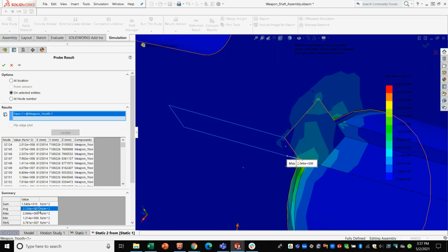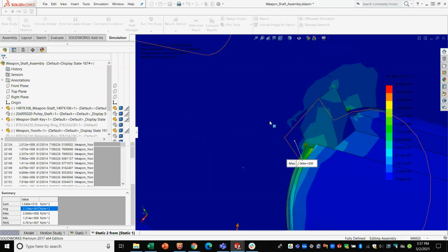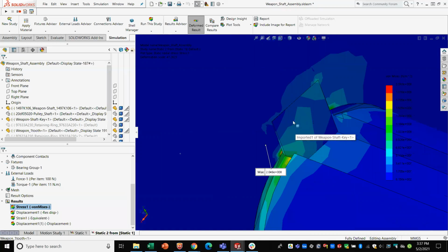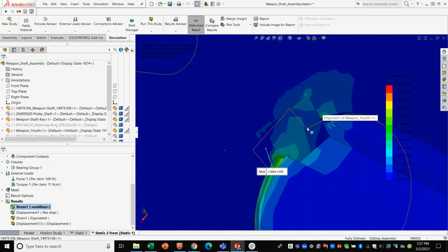Average stress is 2 megapascals. The max stress is 21 megapascals. And that max stress is 10 times higher because it's all focused onto a single node. That's an error associated with the contact. So you average it out basically. You can pick a line to average it across, or a face. You may have to do a split face and then rerun the model so that you can pick the face, that split face.